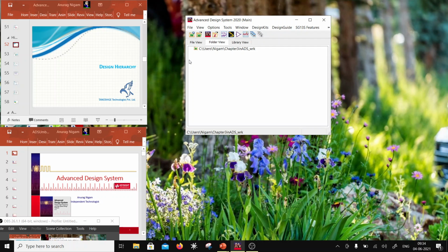And the second thing is that there is no restriction of the supply voltage. So for example, even if you put a supply voltage of, let's say, 3 volts, and you give a signal which results in an output voltage swing greater than 3 volts, maybe 100 or 200 volts, it is going to show you an output voltage swing of 200 volts, right? Now how is it possible? What is the use of such a simulation? Well, as I told you, it linearizes the response. So if the response is linear for any transfer function, high gain blocks are going to give you very large voltage swings, and that can exceed even the supply voltage.